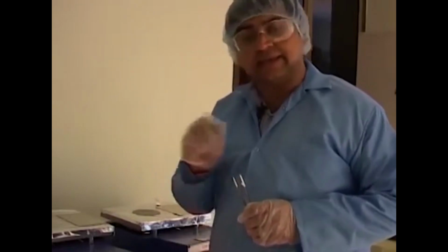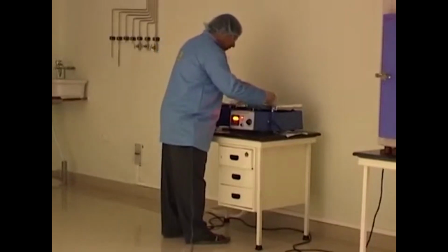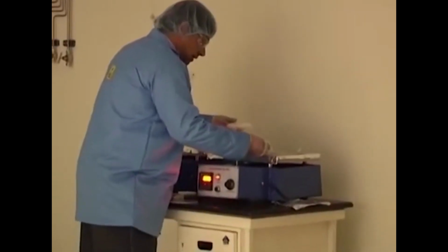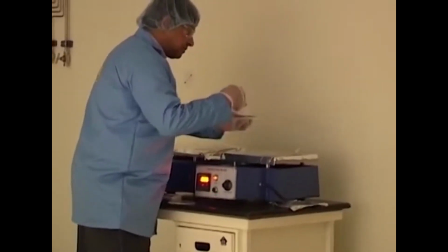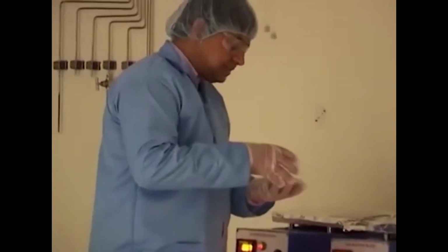slightly contrasted, you can see the different contrast there in the zone which is exposed. When you develop it using a developer solution, those are typically the zones which remain back, and the remaining portions which were unexposed would go away, and that is essentially what a negative tone resist is supposed to do on the wafer surface. So we are going to now pick up this wafer from this particular place, and we have now completed more or less the whole exposure and post exposure baking steps, and essentially we are now ready for the next step in the process, which is developing.